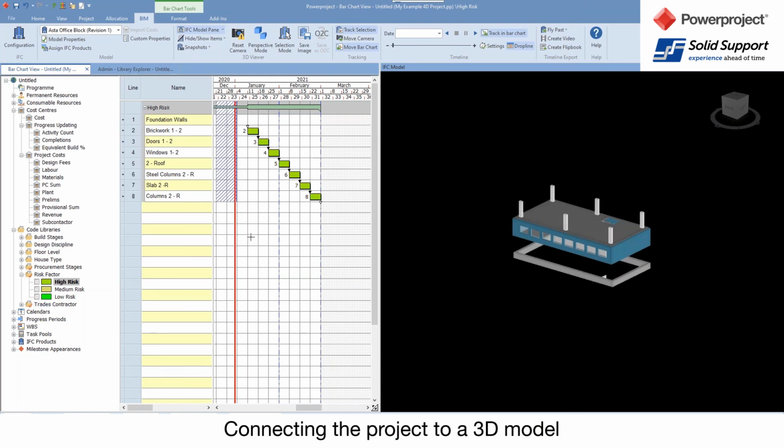And you can also export out to P6, but obviously the BIM side, the IFC and 4D stuff, is not something P6 handles; it's not part of its XML or XER format. But there are ways you could keep a master of your Powerproject and bring in the updates from P6. We've even got people that use the free viewer to import XER files to view them, because they don't need a P6 license to do it.